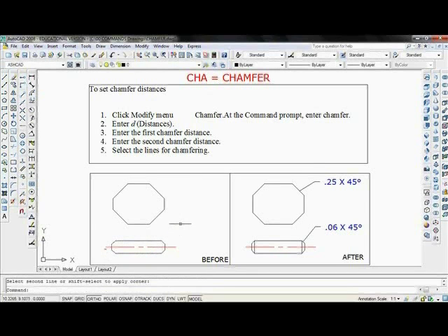and again here. And since this is a shaft, and looking at it from the outside, there should be a line here. So I'm going to put a line with object snap on from here to here, enter, repeat the command from here to here. And the drawing looks correct, so we'll move on.